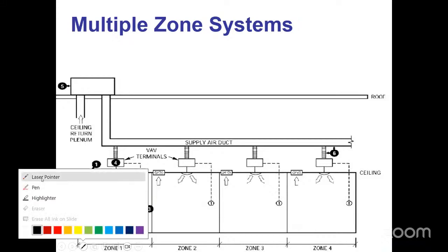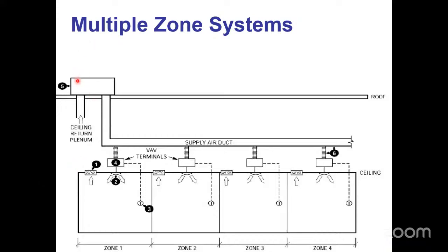or it could be several of them, right? Depending on how big the building is. A single air handler mounted in the building or on the roof, package rooftop unit, that's VAV style. We'll talk about what that means in a minute. Providing cold air down the duct. And then each individual zone will have its own branch coming off the duct like you would normally have, but there'll be a damper inside there. So there's a VAV terminal. I'll show you some pictures of it later with a damper in there that lets more or less cold air into the system. So that's a VAV system.